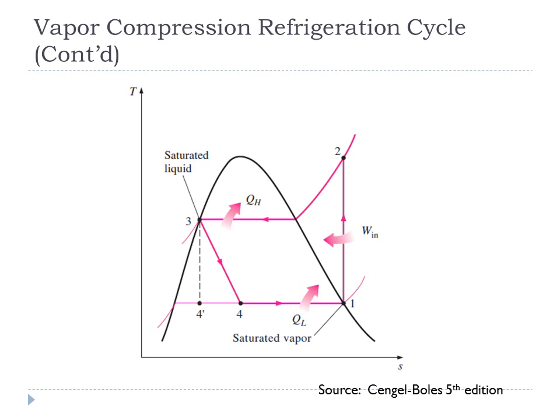Not only temperature, it is pressure which is also increasing. So the pressure at point 2 is very high. Now 2 to 3 is the process carried out inside the condenser, and we can see that the temperature is decreasing, but this line is a constant pressure line, so from 2 to 3 pressure remains constant.